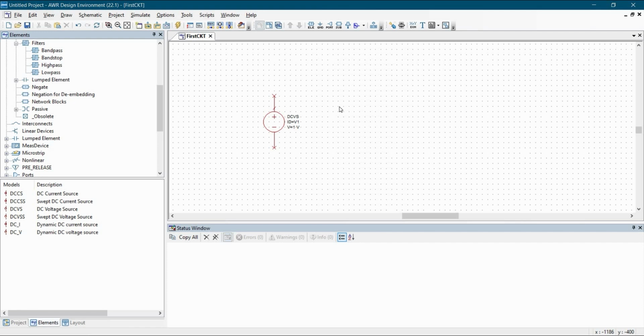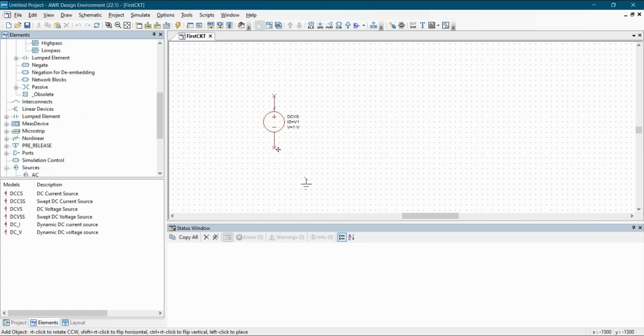if you wanted to remove any component. So after placing this DC source, we are just going to add one ground on it on the negative terminal. So you can directly place ground from here. You can search ground here from this tab or press Ctrl L and place element from that. So I'll just place one ground on the negative terminal of VDC.